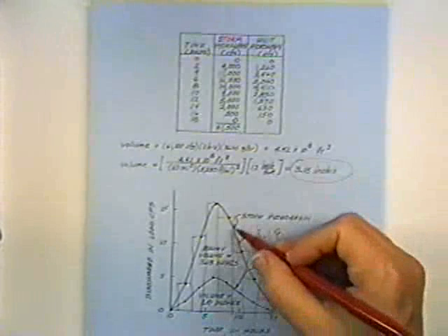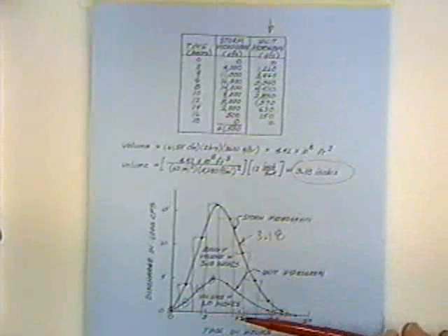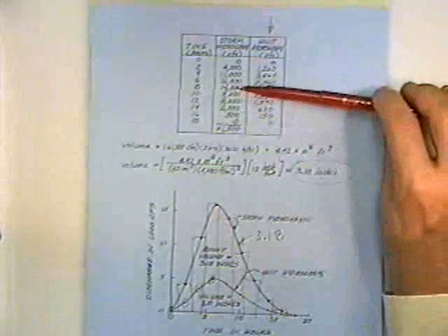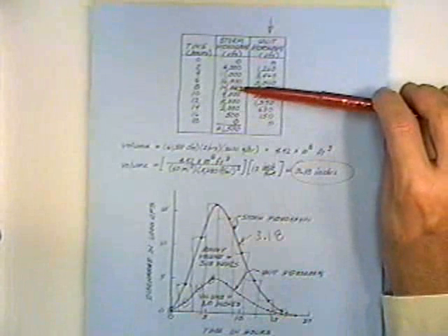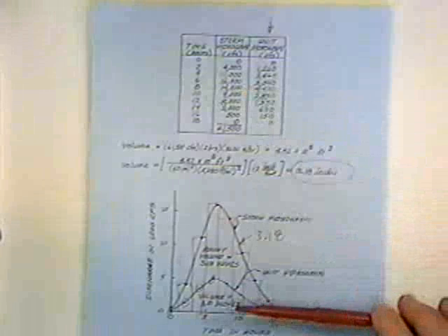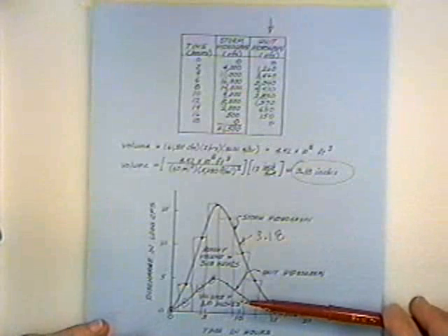So you divide each of those ordinates by 3.18 inches, and you get these ordinates. And that's what we've done in this column. These ordinates represent a hydrograph that has a direct runoff volume of 1 inch. The important thing we need to note is that the original hydrograph was created by a rainfall event with a rainfall duration of 2 hours. And so this is a unit hydrograph for a 2-hour duration rainfall event.